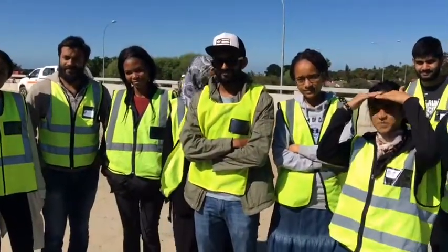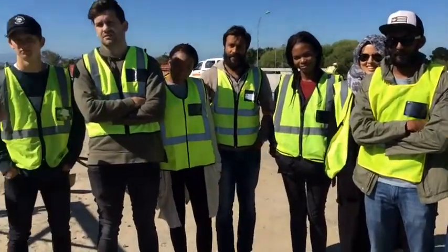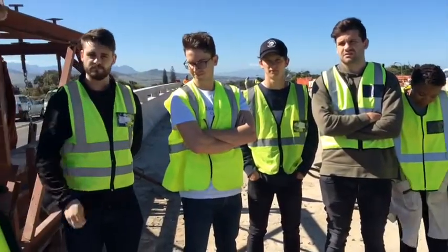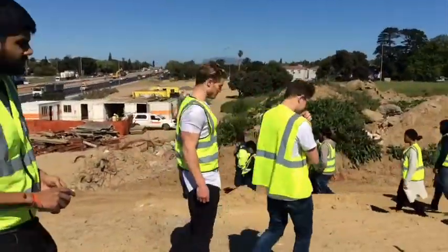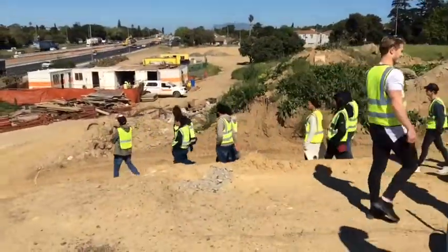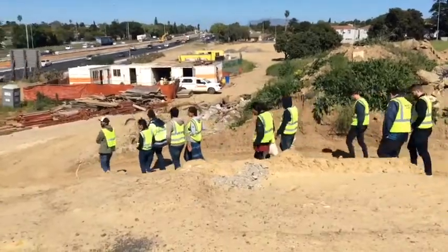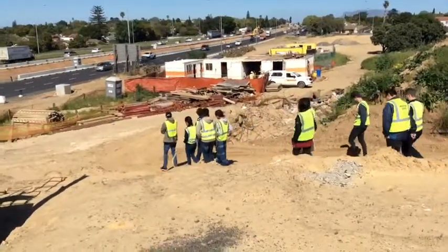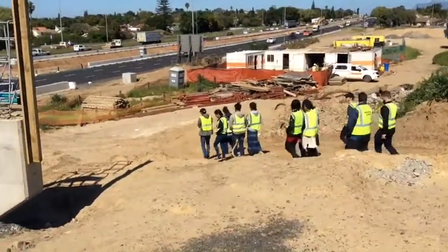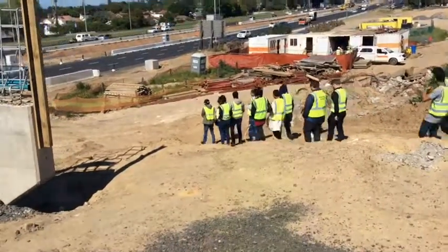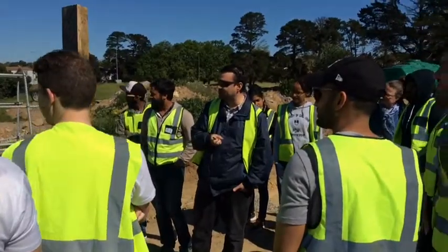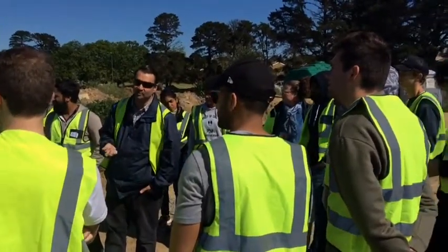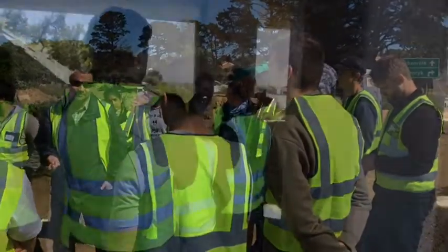This assignment has allowed us to gain a better understanding of the SANS 1200G document with regards to measurement of concrete works. When comparing the order of measurement, the engineers often deviate from the specific order set out in SANS 1200G. As observed in comparing the Bill of Quantities with the SANS 1200G document, many of the units of measure do not comply with the recommended units. This may be in part due to typing errors that were made during the compiling of the bill of quantities.